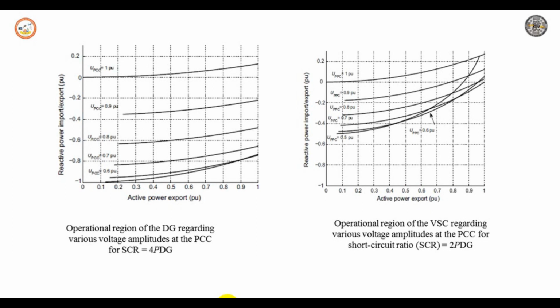First is the current amplitude, limited in order to protect the semiconductors of the voltage source converter through overcurrent protection. This limitation highly impacts the compensation of PCC voltage using the injected reactive power of DG. Since the maximum available active power from DG is usually injected to the grid, only a small amount of reactive power is available without violating this current limit. This eventually means that certain voltage quality phenomena at PCC may not be compensated because of the lack of reactive power.